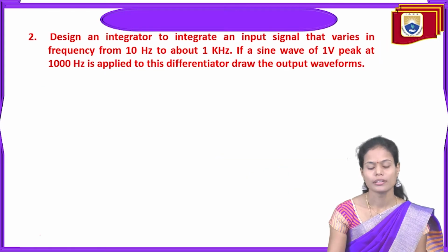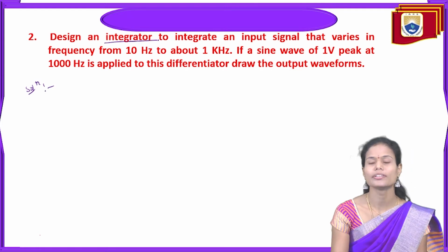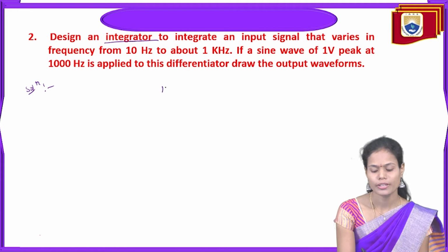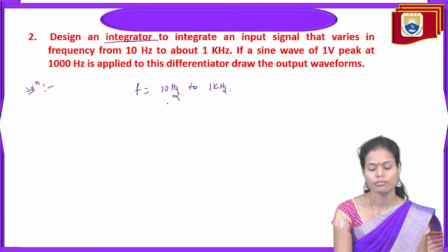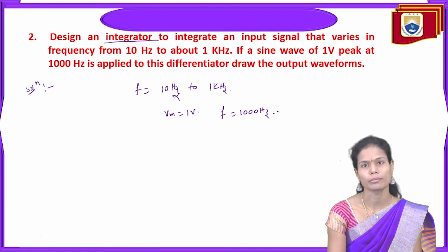And next, the problem related to the integrator circuit. Design an integrator to integrate an input signal whose frequency varies from 10 Hz to 1 kHz. If a sine wave of 1 volt peak with a frequency of 1000 Hz is applied to this integrator, draw the output waveform.